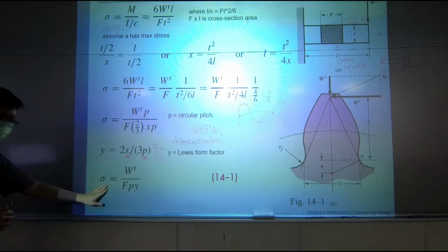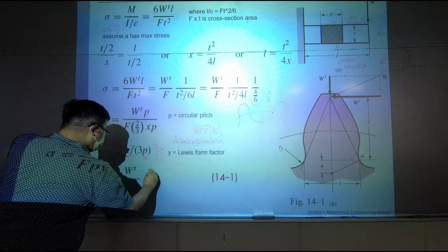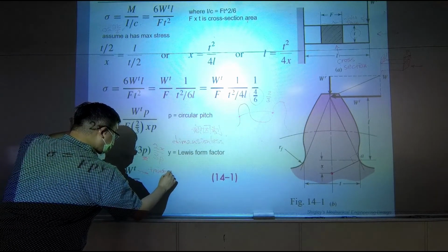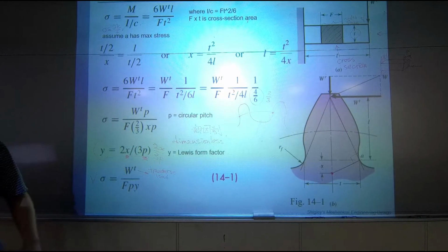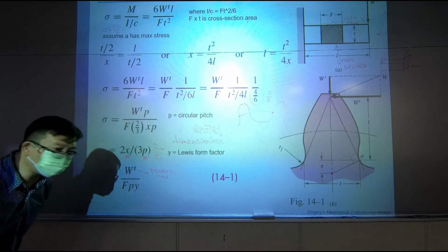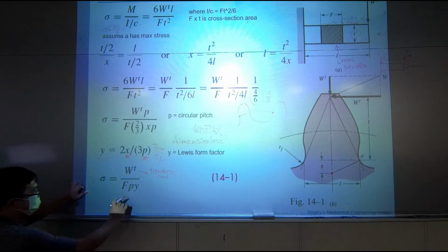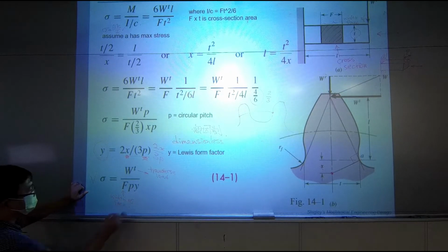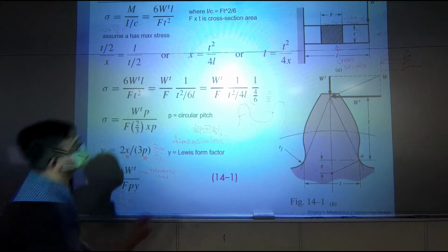So let's take a look at what's inside the stress equation. This is basically the transverse load. Okay? So what's the usual way to define stress? Force over area. So let's take a look at what's this. This is the width of the face. Okay? So what's this? P times what? P is pitch.